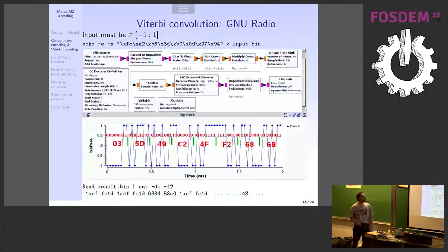Okay, so we've got libfec. We can check that indeed we can decode our word. So if we have the sequence, this is an example that was given to me by the author of GR Satellite, Daniel Estevez. I hope I pronounced his name correctly. You've got the FEC decoder here, as was shown by Martin this morning. And if I feed my GR decoder here with the encoded word, indeed I can get the output, which is 1ACFFC1D, except sometimes I get wrong messages because you see here that my input stream is repeating.